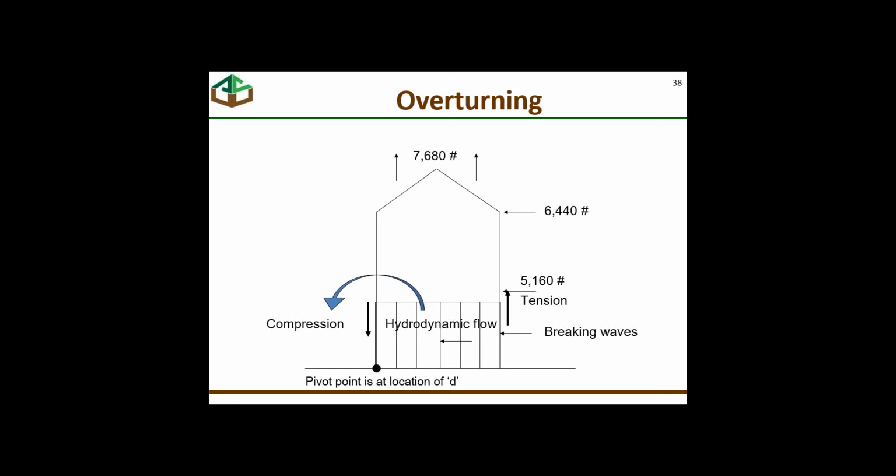Loads times moment arm gets you a moment. There are several places here you could take the moment. I have decided to take the moment down here at this point of fixity because, again, this is a foundation design discussion, really. So I'm more interested in this discussion in what happens to the whole building. I don't want these piles to break off. I don't want them to pull out of the ground. So I'm using the point of fixity as the distance D here. But you could, if you were looking mostly at the box, at the connection of the building to the top of the foundation, you could fix this building about the point where the cursor is pointing now.